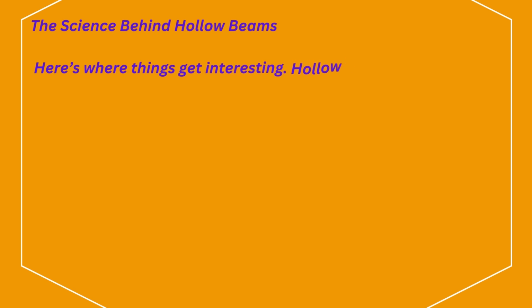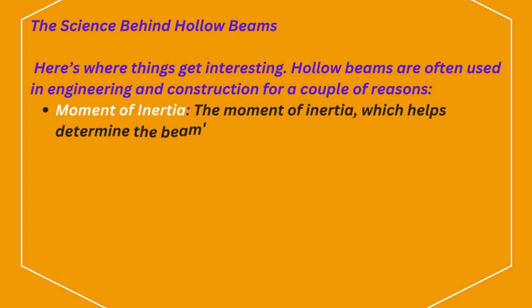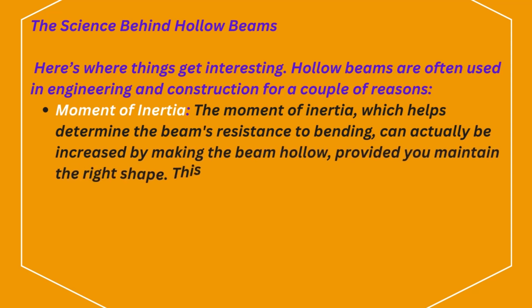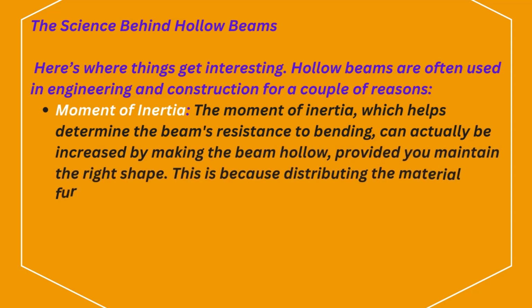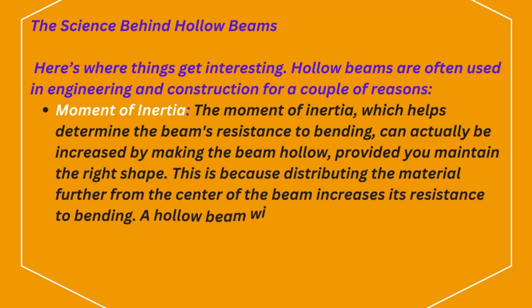The science behind hollow beams. Here's where things get interesting. Hollow beams are often used in engineering and construction for a couple of reasons. 1. Moment of inertia. The moment of inertia, which helps determine the beam's resistance to bending, can actually be increased by making the beam hollow, provided you maintain the right shape. This is because distributing the material further from the center of the beam increases its resistance to bending.